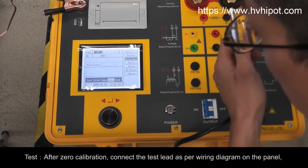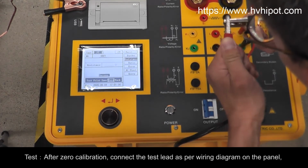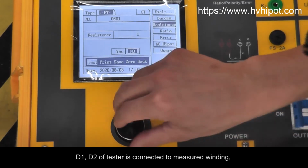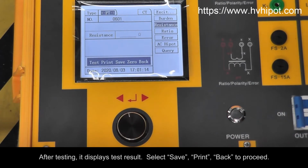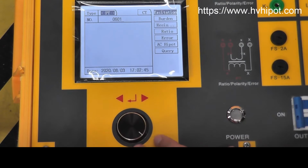Test. After zero calibration, connect the test lead as per wiring diagram on the panel. D1, D2 of tester is connected to measured winding. Select test to start testing. After testing, it displays test result. Select Save Print, back to proceed.